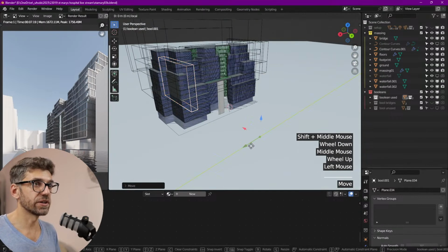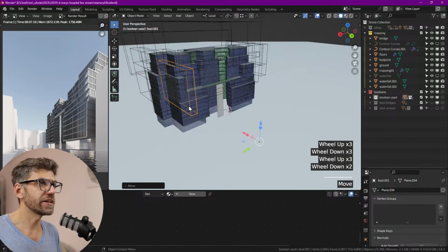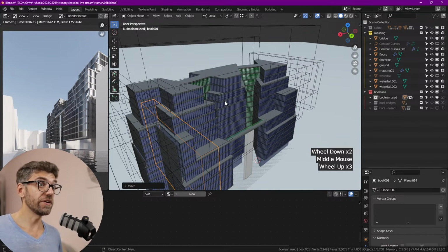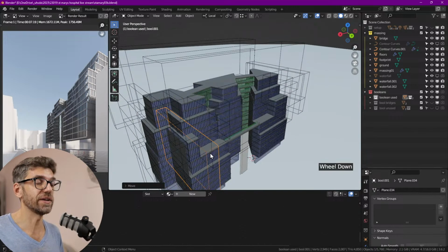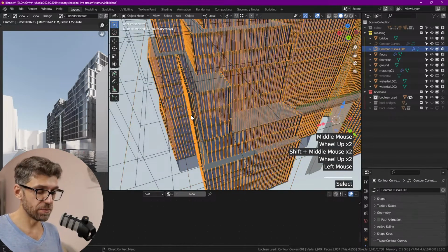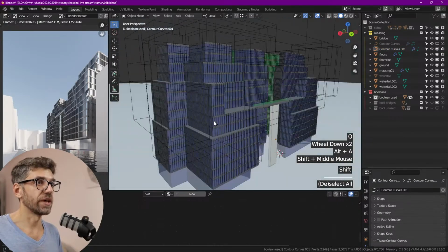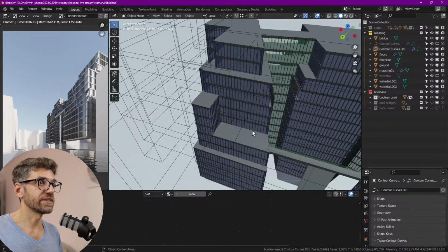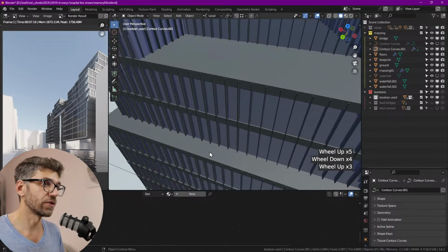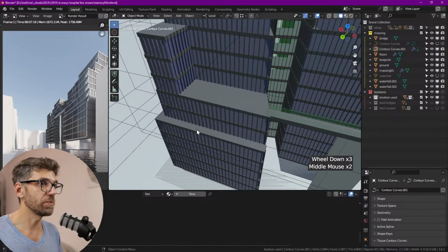And this can be subtle. I'm making these small setbacks just so they break down the volumes a little bit. We might have done it too much. It's interesting, very nice setbacks, but it might be too much, right? So we might need to tone it down a notch. And how would we be able to tell? Most importantly, it's understanding how the structural grid works, more or less, right? Is that spacing too much? Is it too little? Is that gap too much for a cantilever? Or are we going to have two sets of columns along that side, which is going to be quite dense, isn't it?